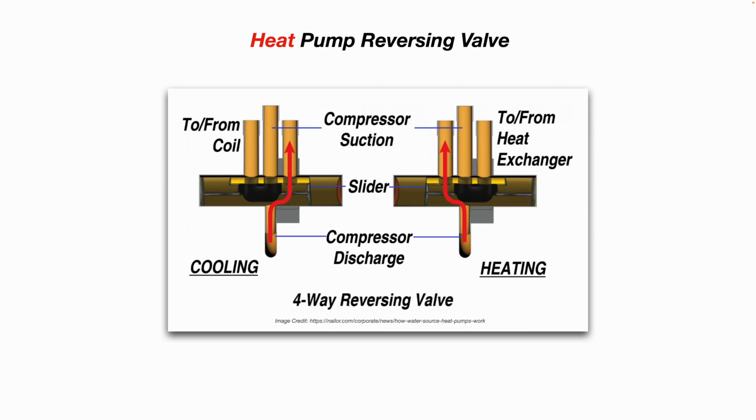So here's a more close-up view of a heat pump reversing valve. You can see in cooling mode the flow from the compressor discharge, and then you can see in heating mode the spool moves over and it flows through a different line.